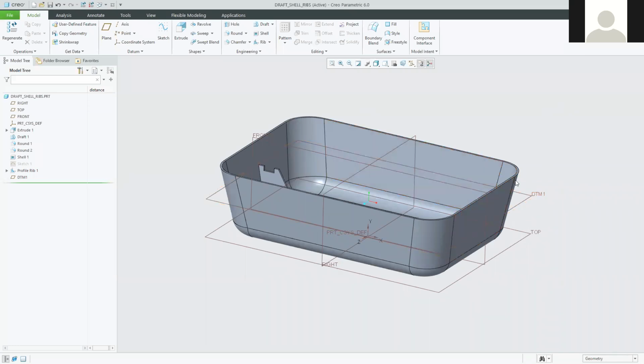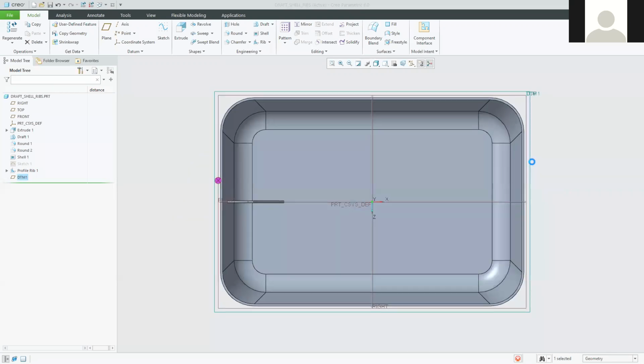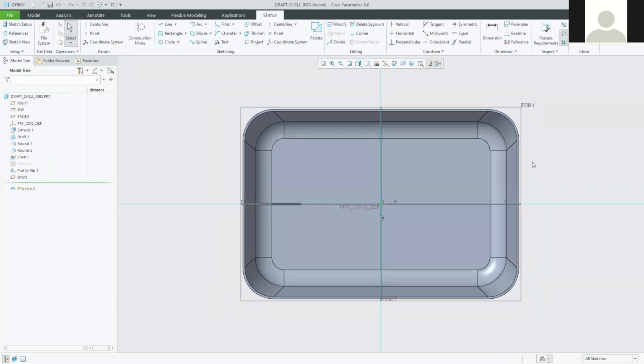So that is what we're going to create our sketch on now. We're going to click on the plane, select the sketch icon, which is the first icon in the middle row of the icons there. Our view should then rotate around so that we're looking at 90 degrees to that plane.